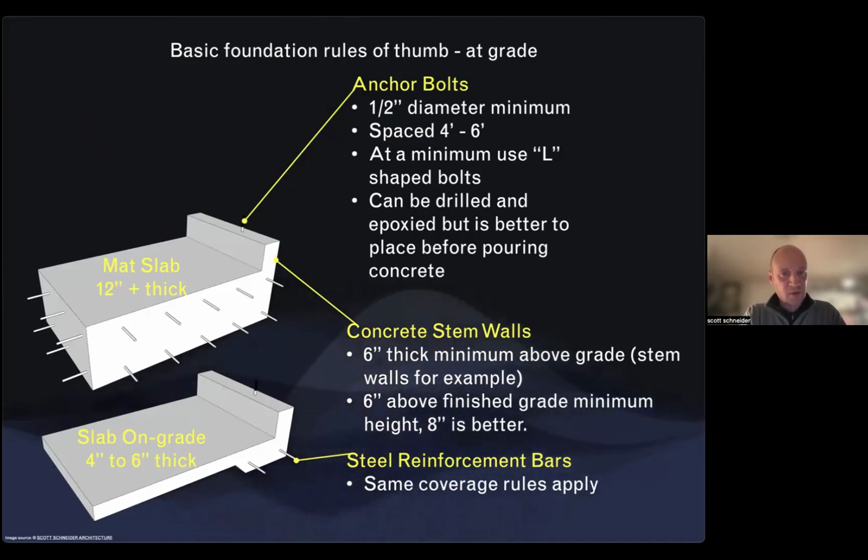You actually have to do that anyway, because as you'll see in some later slides, any wood that's above the grade needs to be at least 12 inches above the grade. I think it's 12. So it's actually good to use concrete down there, and that also helps in WUI zones where fire could be a problem with embers.